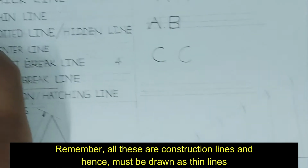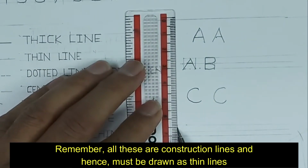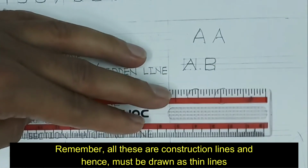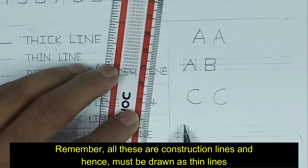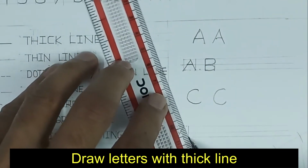Majority of the letters are symmetrical about this horizontal center line, while a few letters are symmetrical about the vertical center line. That's why we draw horizontal as well as vertical center lines wherever required. Now I am drawing letter A. While drawing letter A, we mark its height, which is already marked as 6, and the width of letter A is also 6 millimeter. So I draw another line such that it becomes a square of 6 by 6. As letter A is symmetrical about the vertical line, I mark another line at a distance of 3 millimeter from this side, and within this I can construct letter A like this.